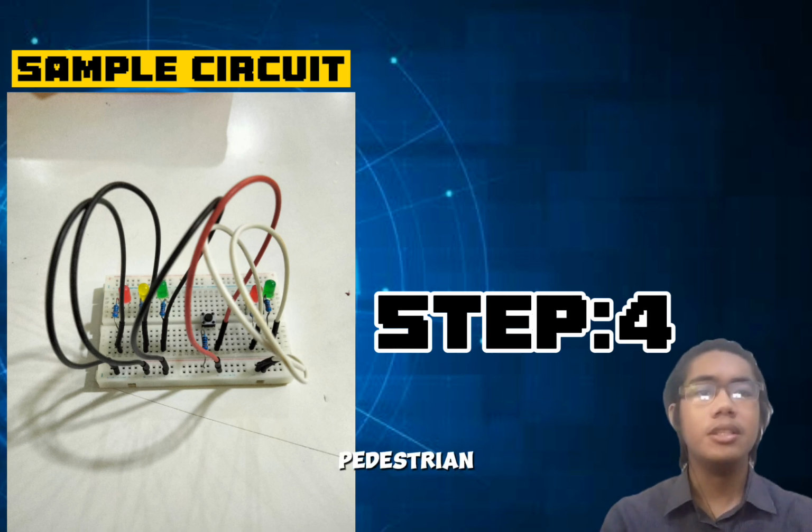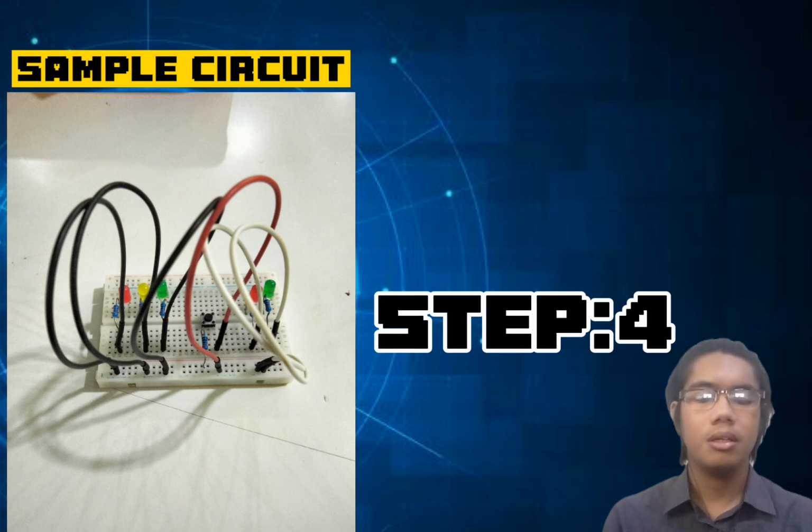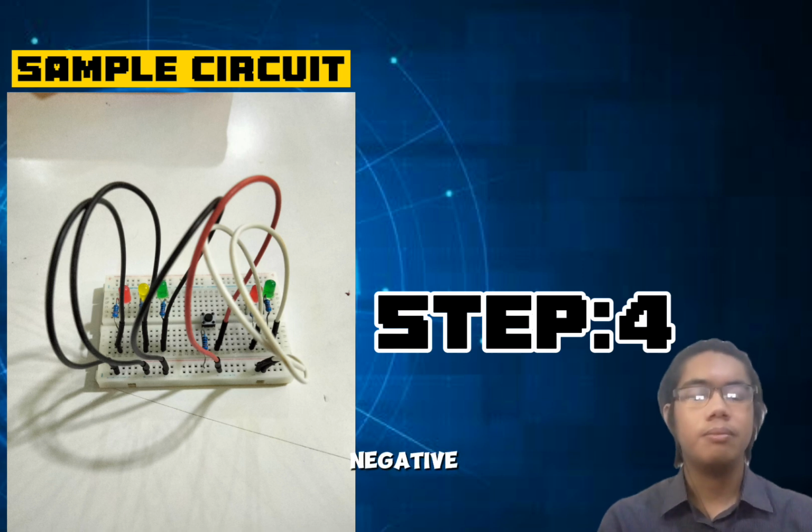And on the pedestrian red LED, connect a white jumper wire from J6 to the negative rail. And also connect the other white wire from J3 to the negative rail. And for the push button, connect a red jumper wire from J12 to the negative rail.